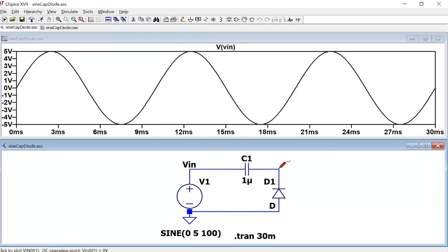You make a case, right? Think about it. If it is lower than 0 volts, what's going to happen? No, when it is lower than 0 volts, for example, the diode is ideal right now, just blocking the current from running in one direction.